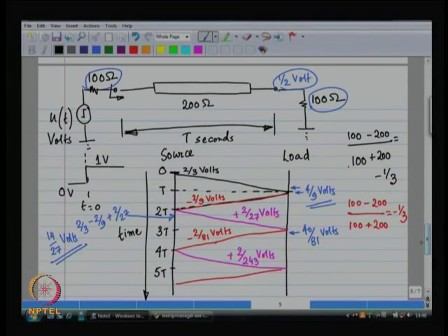in which case all of these reflections that we did in the time domain become much harder to do. Because when the reflection coefficient is a complex number, you have to break up what you had transmitted, you have to break up the waves in terms of sinusoids, and then when it is reflected you multiply by the reflection coefficient, add the phase delay of the reflection coefficient, etc., and then you sum up all these waves and you end up with a big mess.